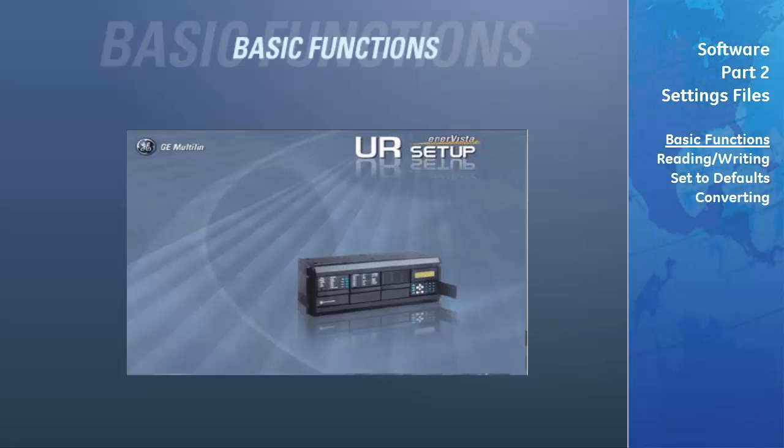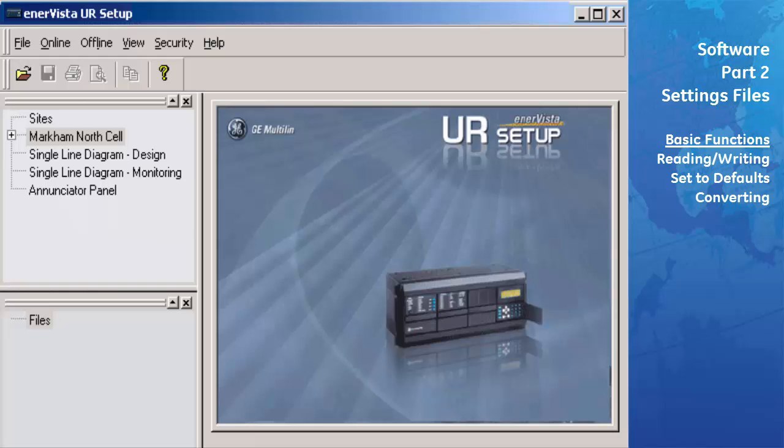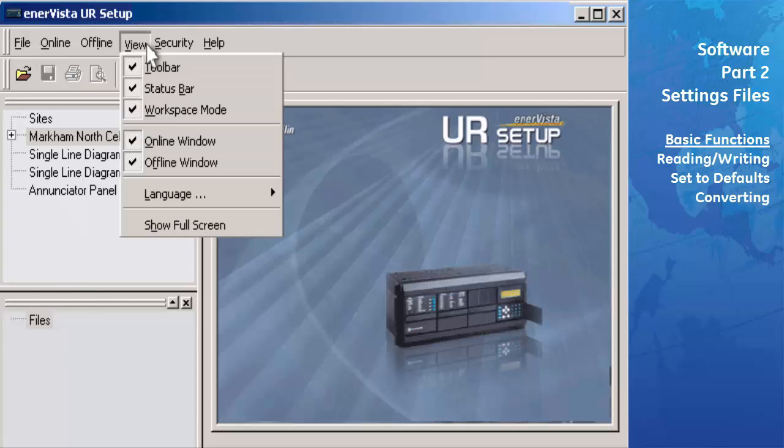Settings files are a convenient way to store and edit offline settings for UR relays. They offer a simple and comprehensive way to create, edit, and save settings for a device in a single file. The operations associated with settings files are grouped in UR-PC under the Offline menu and appear in the lower left panel. If you don't see this panel, open the View menu and check the Offline window menu option.